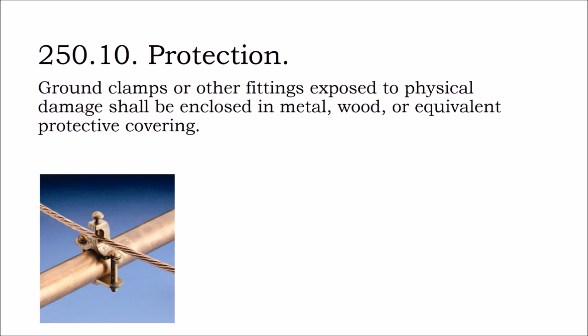And there may be some impedance from the soil. So getting a copper pipe 8 feet long driven into the ground gets you a little bit more conductivity, a little bit less resistance. Well, so you'll run your bare number 6 down to the ground rod on the side of the building, and then you'll use, the construction jargon for this is called an acorn. It kind of looks like an acorn, I guess. But to connect your ground up to it, it has to be protected, because someone could come along and kick that thing, and all of a sudden you have an ungrounded system.